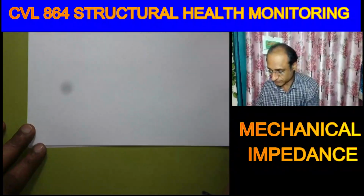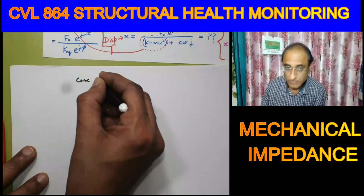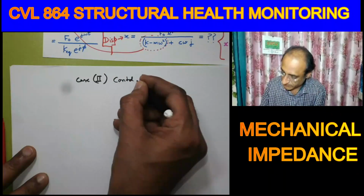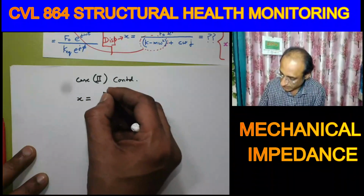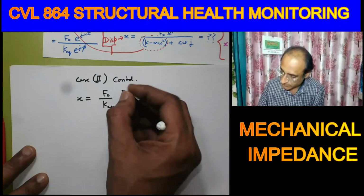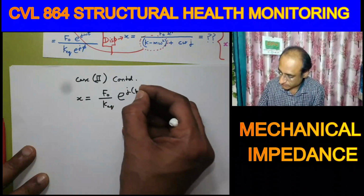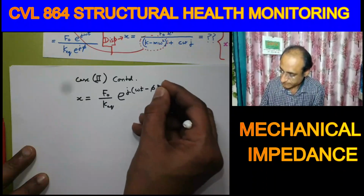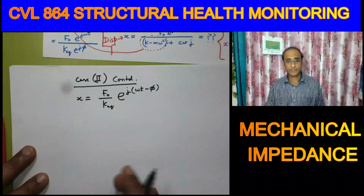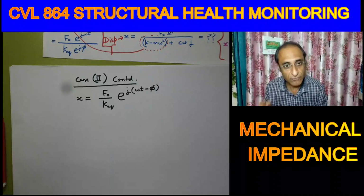So in case 2, your displacement will be equal to F0 divided by the equivalent stiffness, and here we have e to the power j omega t minus phi. So that is for case 2. So what do you infer here? That x, the displacement, will lag behind the force.